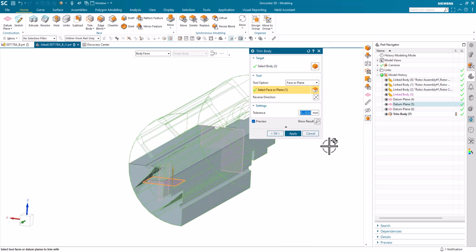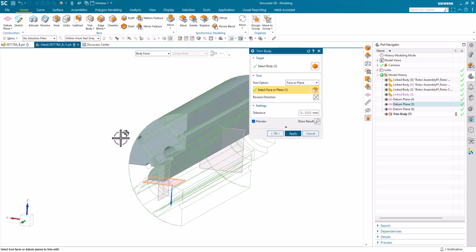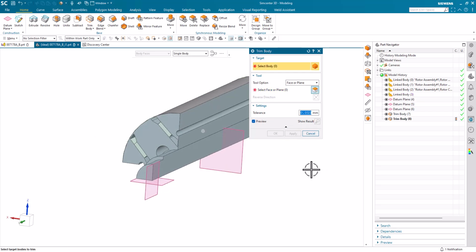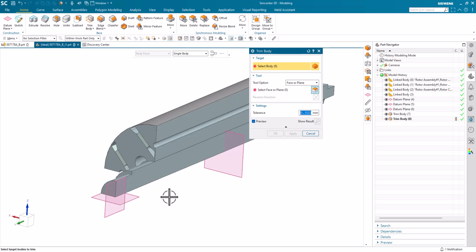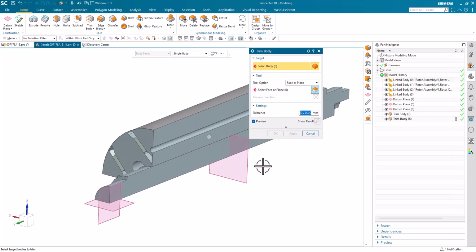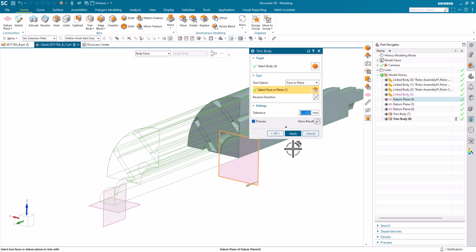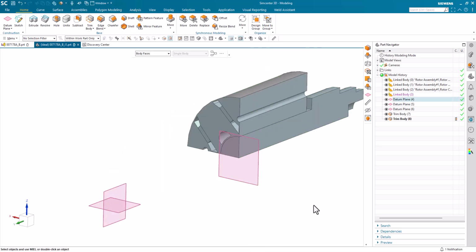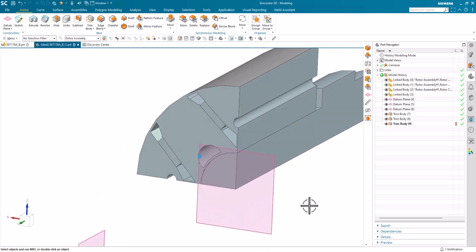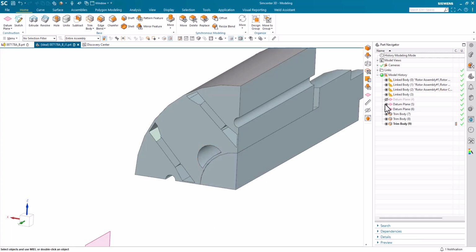Pick the horizontal plane, and now I've got my 90-degree sector that I'm interested in. So I'll apply that, and then I do want a planar face that I don't have just yet for the plane strain. So I'm going to trim all these bodies. I'll say select all, and pick this plane, and then good to go. There's also some defeaturing that I want to do.